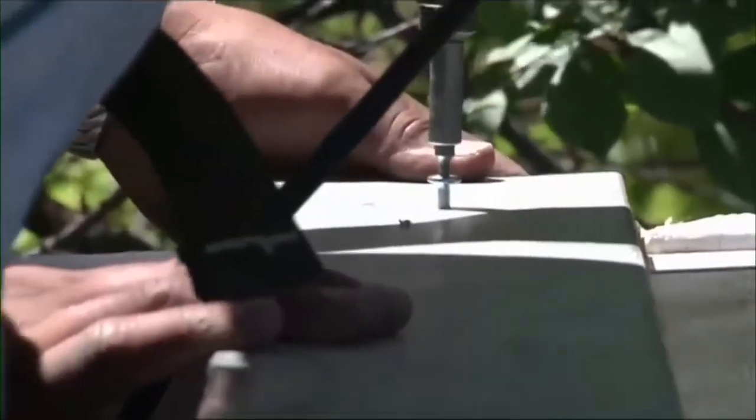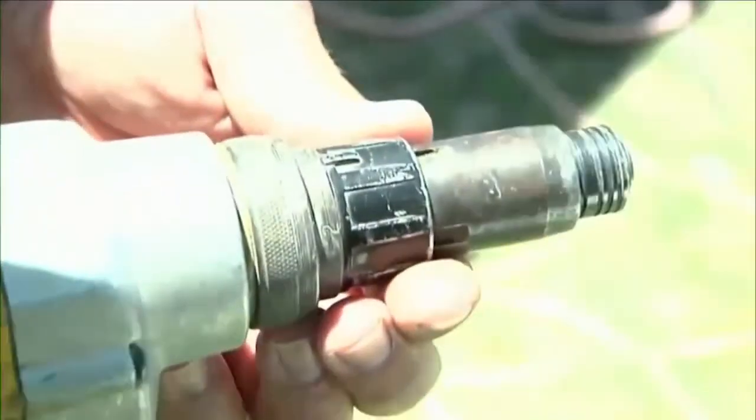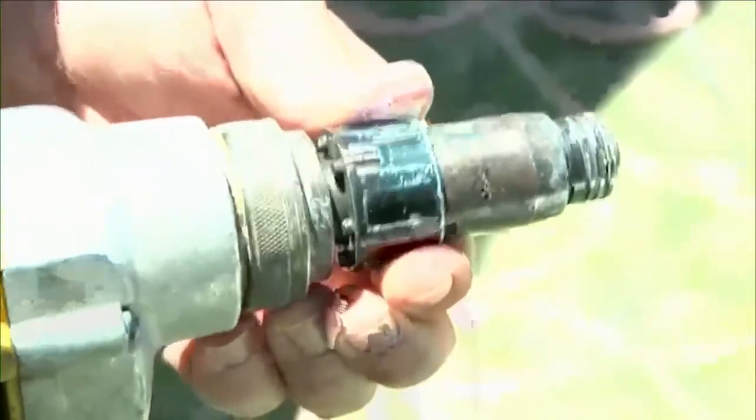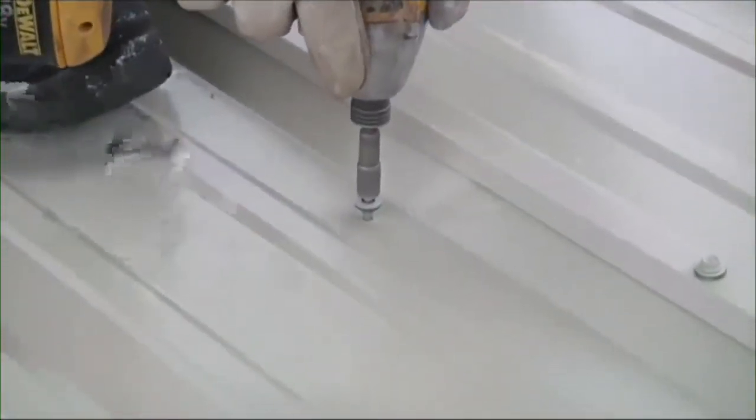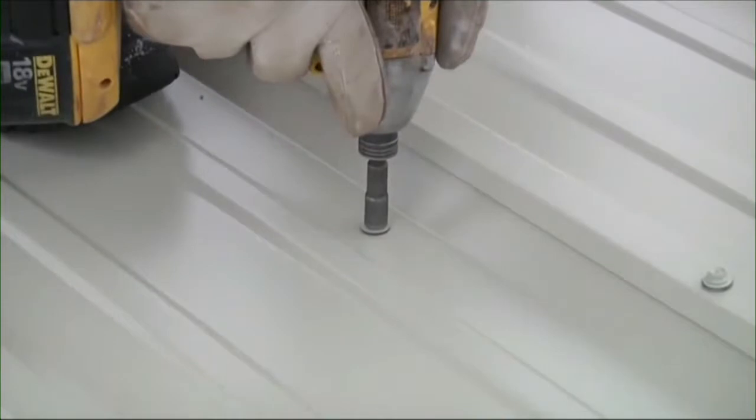The Sealed and Safe fastener has been specifically designed to be used with the Sealed and Safe thermal block system. Use of the fastener is mandatory as it is key to the performance of the Sealed and Safe thermal block system. The 6 amp 2500 RPM electric screw gun will be needed with a depth locating nosepiece. Most screw guns run at a higher RPM and will need to be adjusted so that the drill head of the screw functions properly. Once the insulation blanket and the roof sheets are placed over the thermal block, Sealed and Safe fasteners are screwed through the roof sheet, insulation, and thermal block into the purlin below.